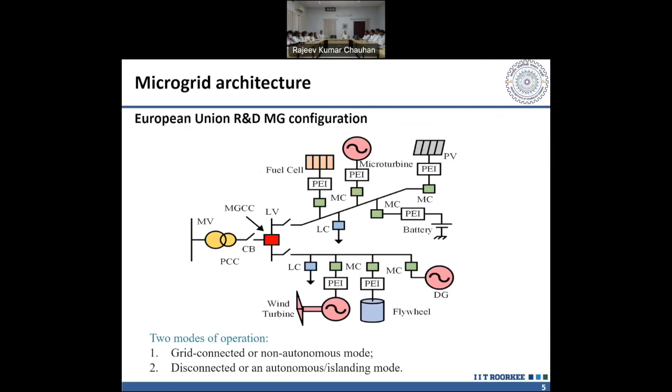In case of the wind turbine, you will have a variable frequency, which must go to a fixed frequency. So first we convert to DC, and DC will be converted again to fixed frequency AC. So that's why we say in all kinds of renewable sources, a very strong power electronics infrastructure is required.